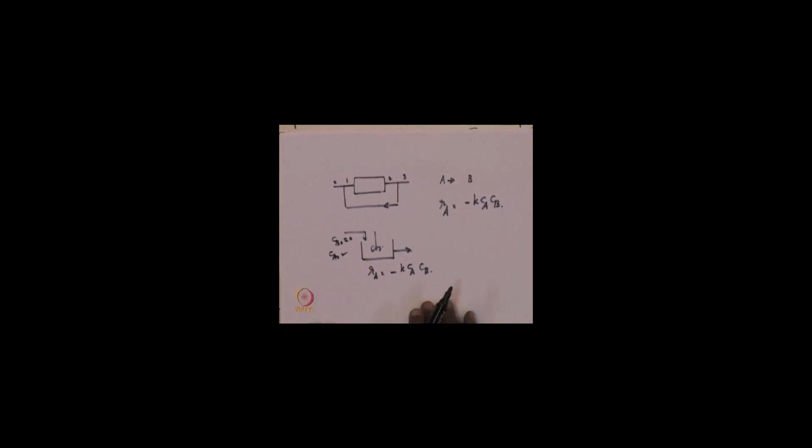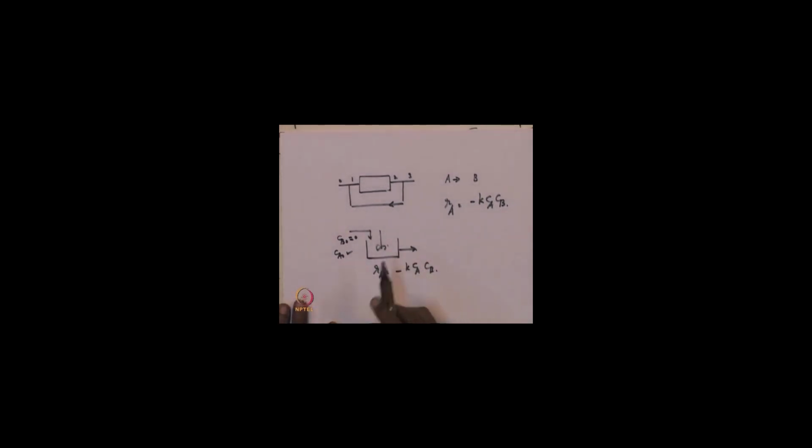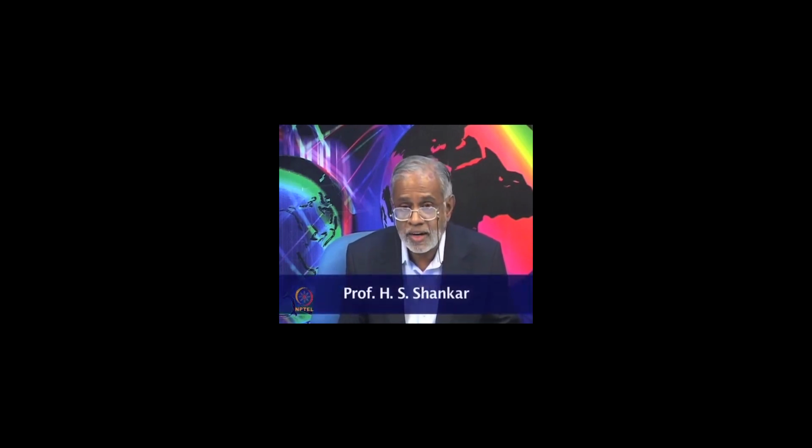We have explained this last time when we met, when we said this is because when you look at the unsteady state during the startup, as long as during startup you have put in some C B into the process, then the stirred tank remembers that startup addition of C B, and therefore, that process will be able to get initiated because of the presence of even traces of C B in the equipment. Okay. In other words, the stirred tank is an instance of a reaction equipment where you do not need product to be primed into the feed as for an autocatalytic reaction.